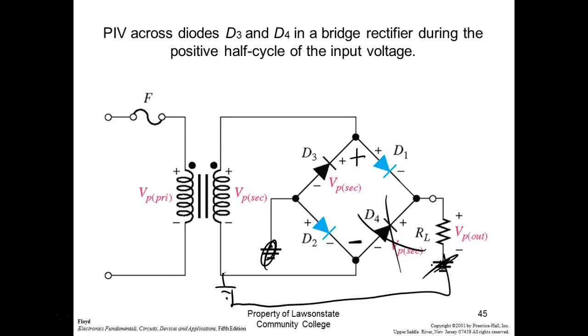So I just created a negative supply, so I need to shift my ground, or my common, up. And all I did was change my reference, right? Of course, now we got to resync our oscilloscope. There it is. So now we got negative DC. If I wanted positive DC, I just change my common, right? So I'm going to come up here and change my common over to this side. Now we got positive DC. And these are full-wave bridges.